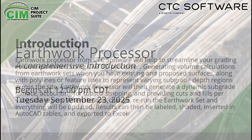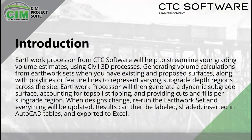So Earthwork Processor was developed to help streamline your grading and volume estimates. What we do is we generate volume calculations from earthwork sets that we create, and we have a proposed surface and an existing surface, and we can use polylines or feature lines to create those regions, and they can represent varying grade depths across the site.